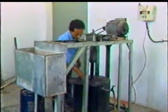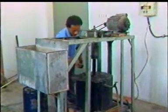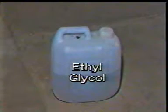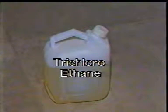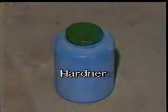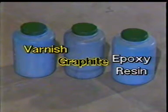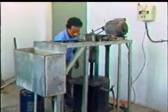First of all, a mica strip of a size depending upon the cutting die is coated with carbon resin. Carbon resin mix is prepared by stirring black pigment, ethyl glycol, trichloroethane, and a hardener apart from other ingredients like varnish, graphite, epoxy resin, etc. for 24 hours or more.